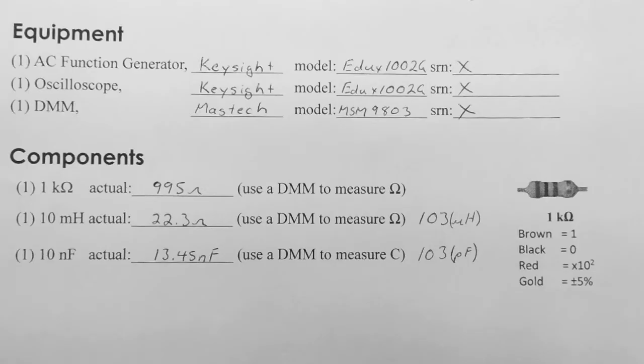And it's a non-electrolytic capacitor, which means it'll be labeled with a number like 103. And 103 refers to picofarads. So that ends up being 10 nanofarads. Remember, resistors have a tolerance of plus or minus about 5%, where capacitors have a tolerance up to 10% or more.